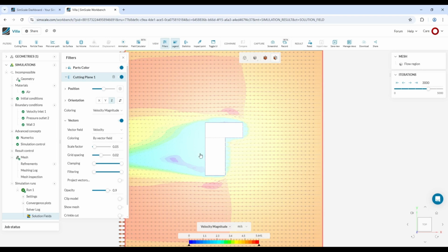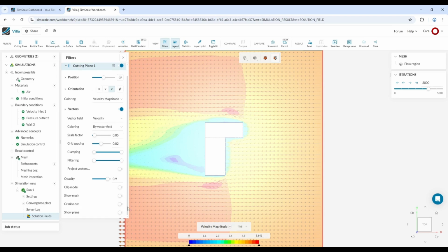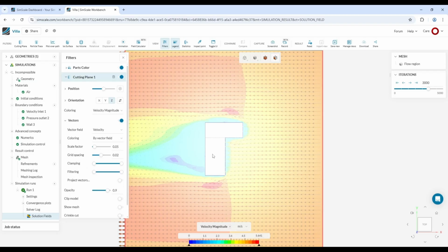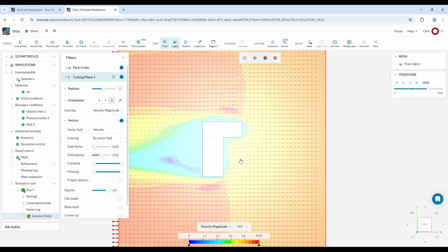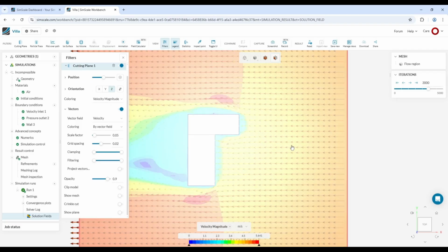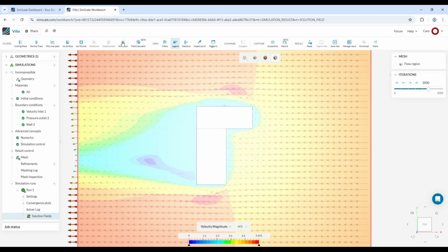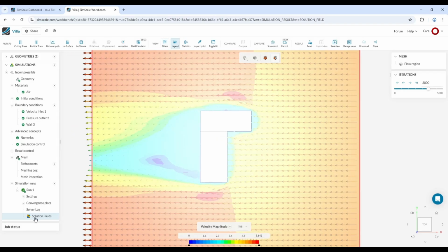From the results, I could see that wind accelerates in certain areas around the building, which could lead to discomfort. Based on this, I introduced design strategies such as planting and buffers to reduce wind impact and improve outdoor comfort. This process helped me move from intuition to evidence-based design, using simulation to support spatial decisions.